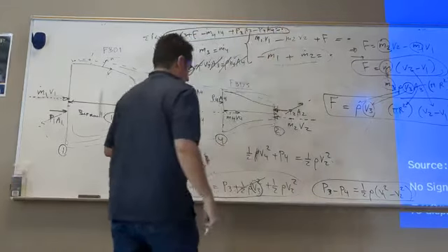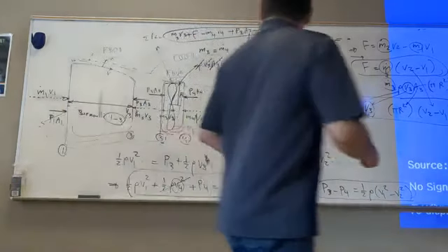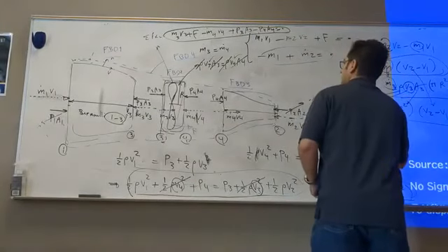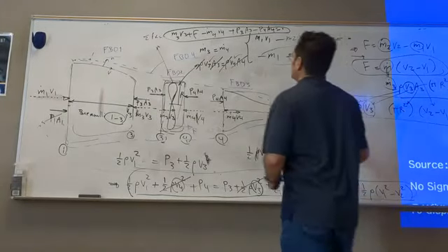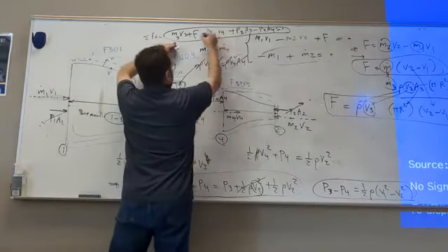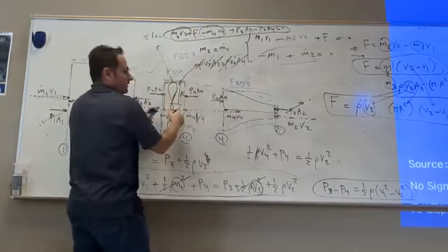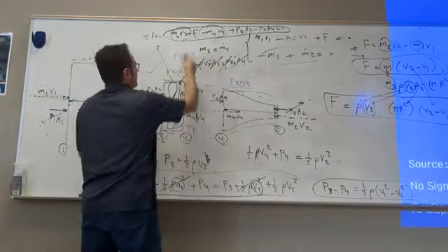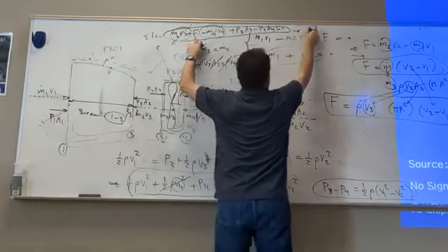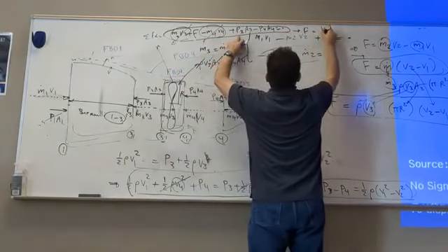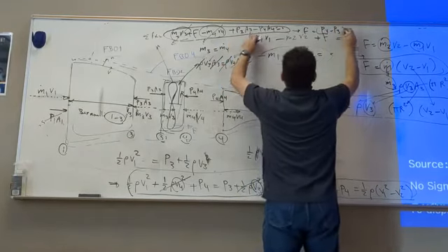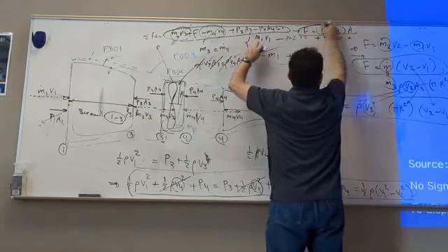Look at that. So that means your m dot, you see, m dot 3 and 4. What's this difference? m dot 3 and 4 difference is 0, right? Because both of them are same here. So this is 0, so you get F is equal to P4 minus P3 times both area is same, call it A.